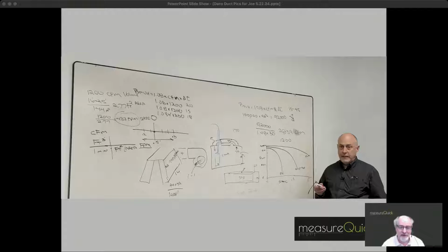We are focused on, do you understand some principles? He makes sure you understand how you got a CFM out of that register. How much CFM do you need based upon BTUs? That goes back to design. That goes back to pounds of air. There's a variety of stuff going on with how to make sure that you have the right airflow that's intended for your system. That of course starts with a really good design.